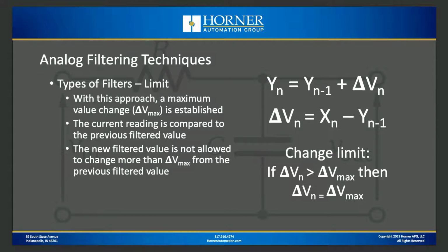So by going through this technique, you can knock off those quick transient responses without losing some of your ability to respond to a step change. This is another technique that you can use, and I haven't implemented it here in Logic, but I wanted to tell you about it.